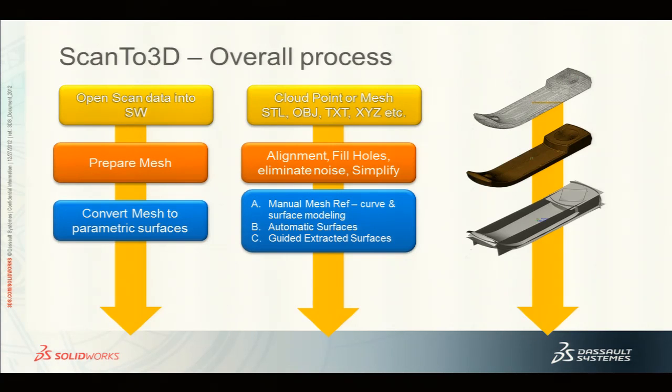And then guided surface extraction. This is the method for product design or machine design. When you have a machined part or a product type of part, you want to extract the analytical and algorithmic faces that make up that and reverse engineer it. And we can do that for you, where you can see in this handset, you can actually extract the planar, cylindrical, toroidal, ruled, and B-spline surfaces from that, and then trim, knit them, and make it solid and add the radiuses back. Okay.